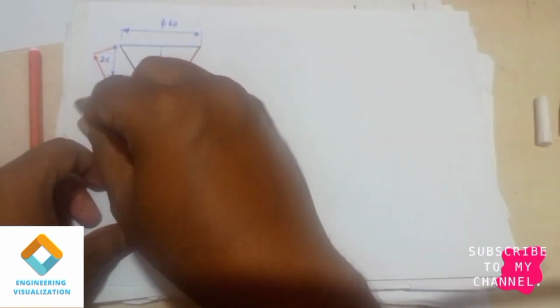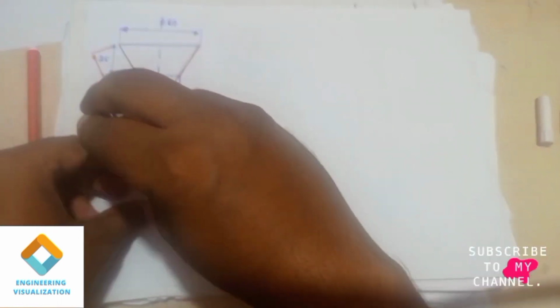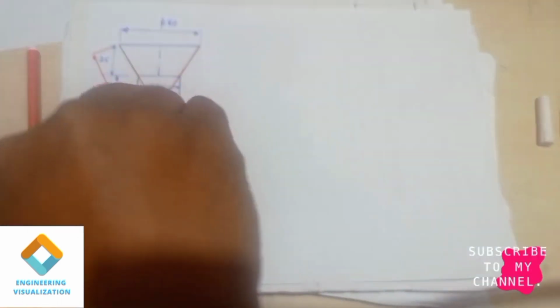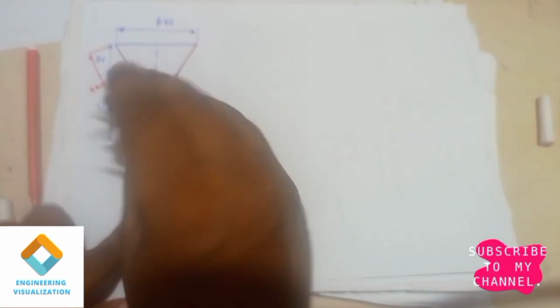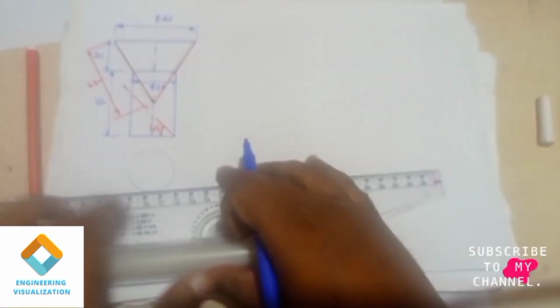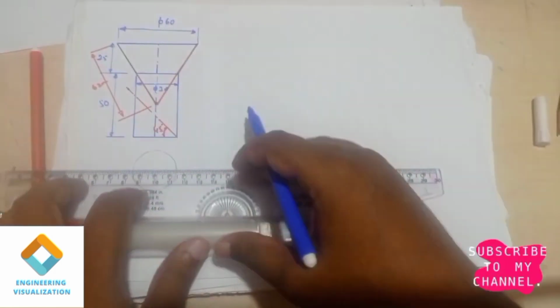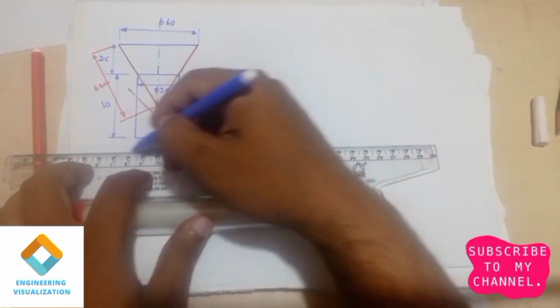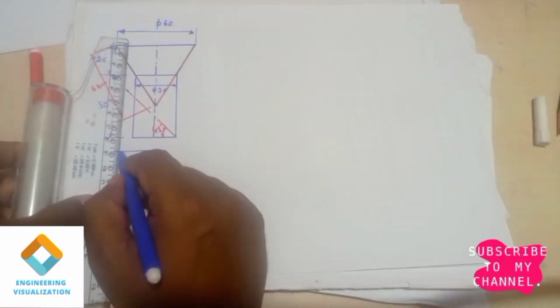So we need to project that axis downward and then we should consider the center. Here I am taking directly the center point of it. So you need to project that axis downward, take the center point and draw a circle. After drawing the circle, show the dimension. Here we will be dividing this circle into 8 equal parts.